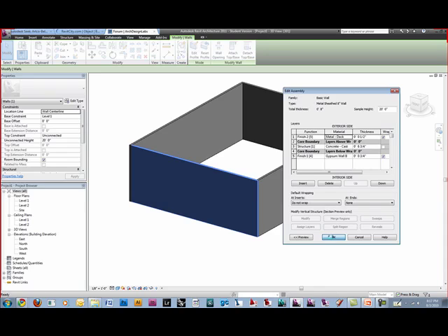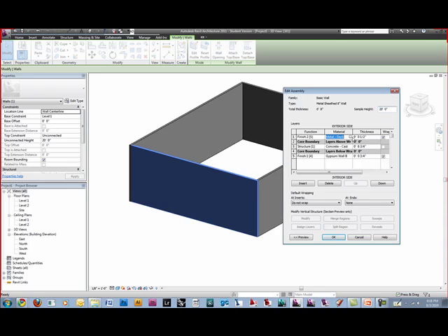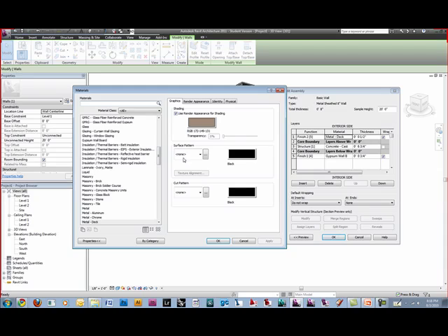It's more about detailing. But also the way you do these layers, it also shows up in plan as well. So if you have 3 different layers, if you go to your plan view and say find detail, you'll see that it has a different pattern for the brick versus the structure versus the finish. And that's also as long as you're setting that up.